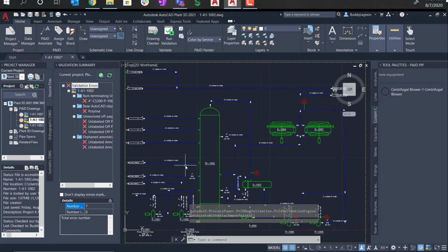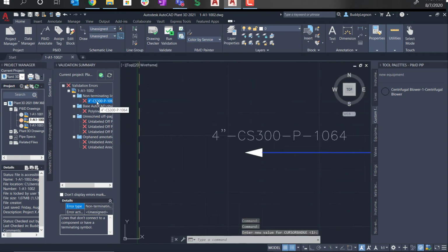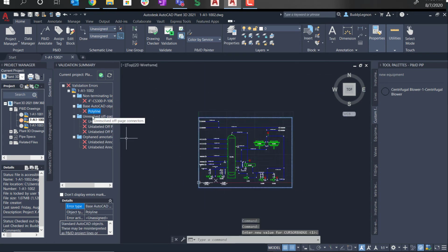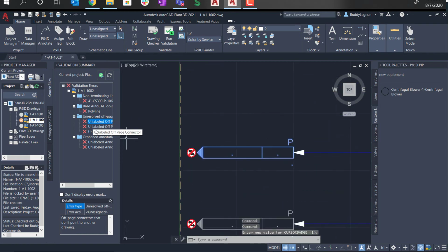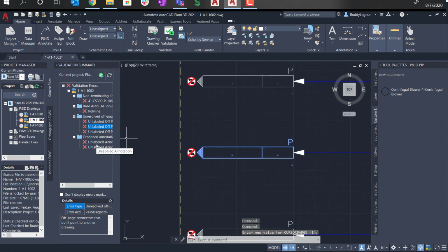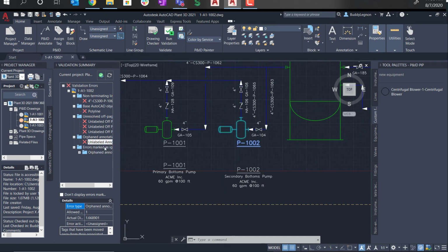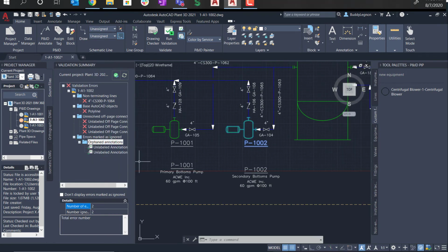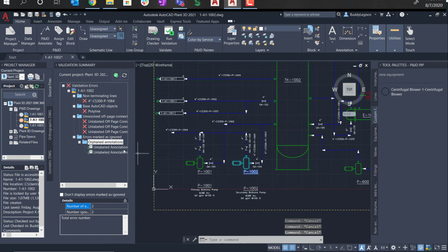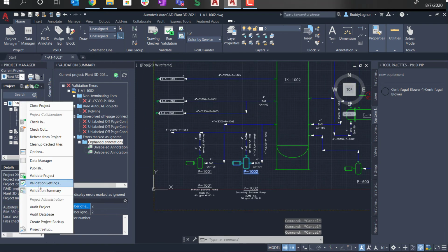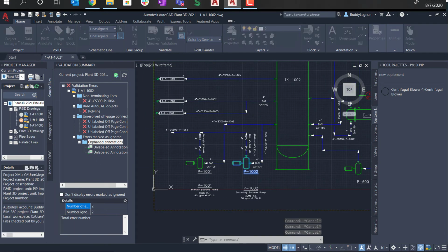In this particular section, I validated the drawing against itself, and I'm looking at the findings. And it found a few off-page connectors that weren't connected, and it found a few pieces of lines that weren't intelligent, such as object lines or construction lines. I can hide those that I don't need to see or that I have intended to create on purpose. As I go through the different validations, I can check off the things that I have accomplished and things that I need to take action on.